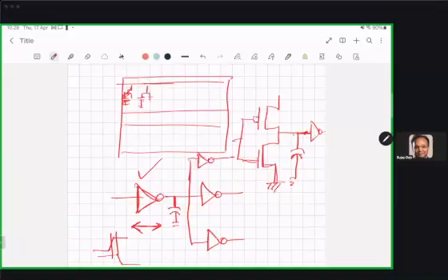So the point I want to make here is that this is called fan out. So when in electronic circuits we mention delay, it's always dependent on what this circuit is driving. If you don't mention that, then this delay has no meaning. Okay, so you can say that, oh, I have designed a NAND gate which has this delay. But then immediately the evaluator will ask you, what was your fan out? What is fan out? Fan out means how you have calculated the delay, how many other elements it was driving.